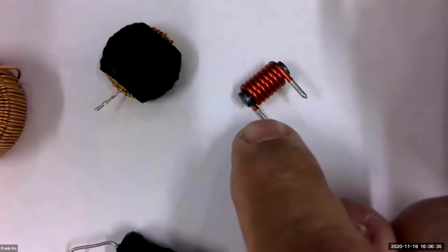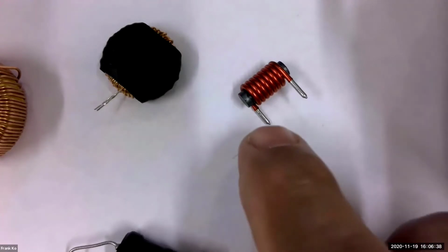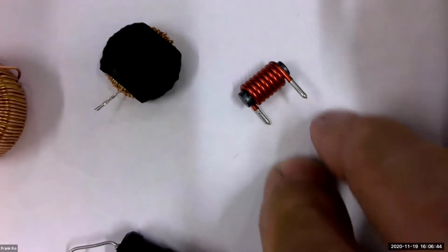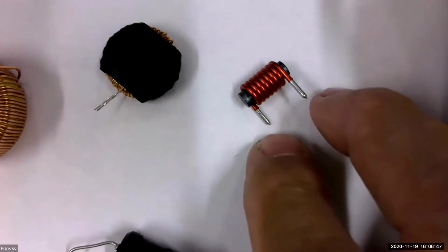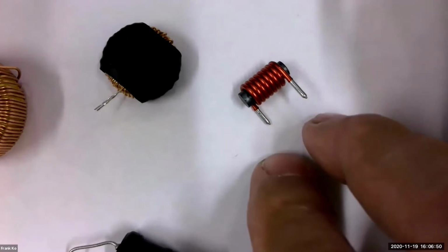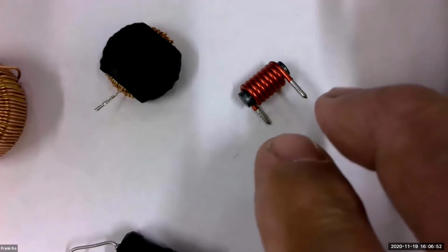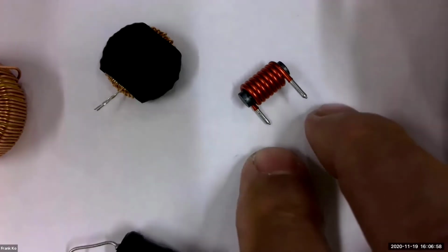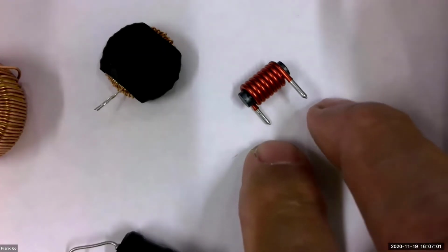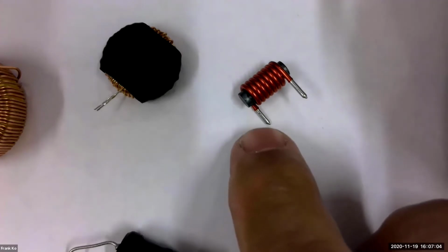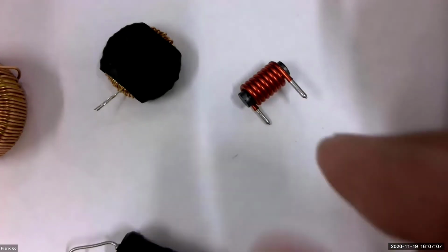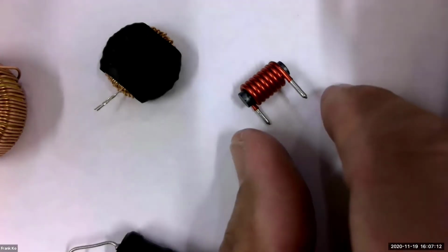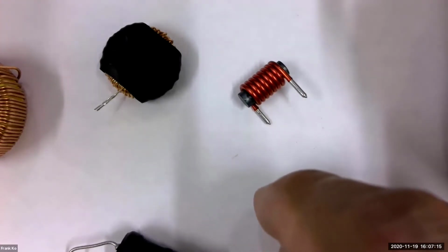They don't store a charge. What they do is they build up a magnetic field. And as they build up a magnetic field, as soon as we release that battery source, then the magnetic field collapses, and it can collapse very quickly. In that collapse of the magnetic field, it can generate a voltage. So it takes voltage to build up the magnetic field, and once we remove the voltage source, the magnetic field dissipates. The terminology that's used is that it collapses, and when it collapses, we're able to determine a voltage between the terminals.